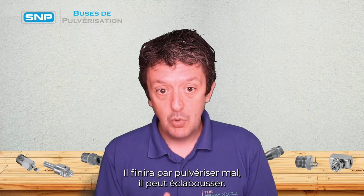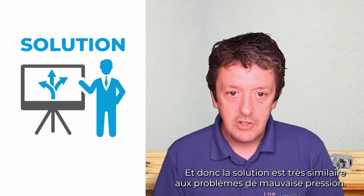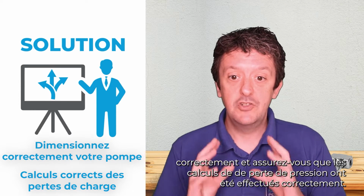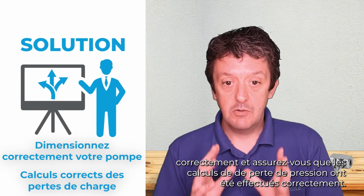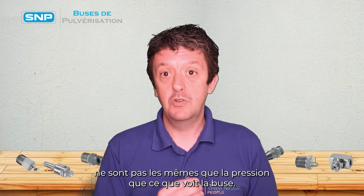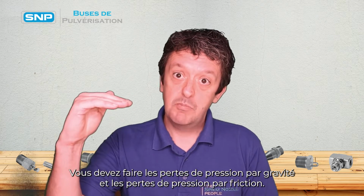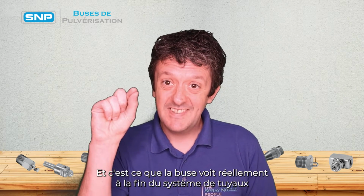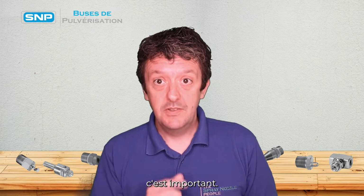It'll end up spraying poorly, it may splutter, and so the solution is very similar to poor pressure problems. Size the pump correctly, ensure the pressure loss calculations have been done correctly, and remember the pressure and flow rate at the pump are not the same as what the nozzle sees. You need to do your gravity pressure losses and your frictional pressure losses, and it's what the nozzle actually sees at the end of the pipe system that's important.